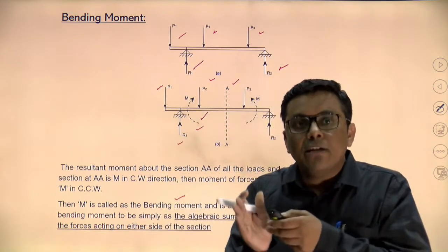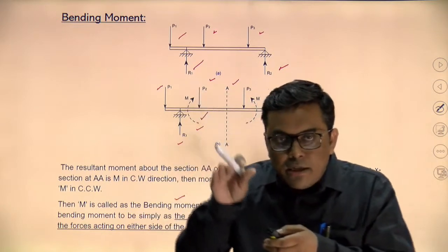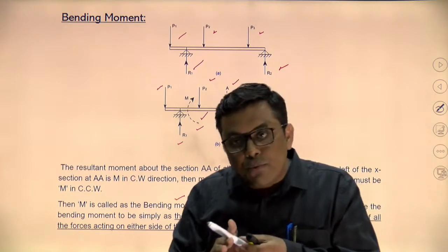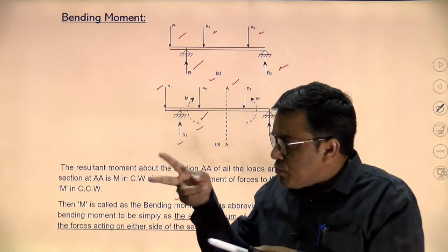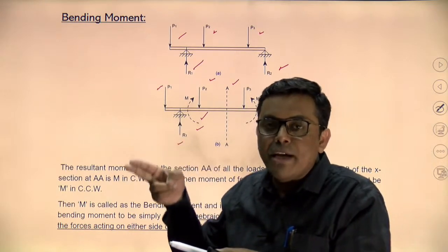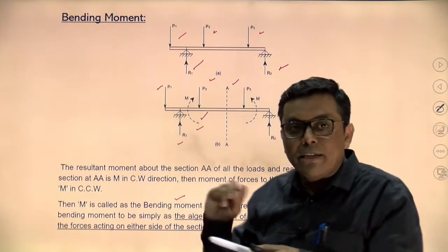On the right side, the opposite of this, for equilibrium purposes. So, on the right side, if the resultant is downward, then it will be considered as shear force, because both will produce a scissor-like effect. If one arm of the scissor is going down, the other one is coming up, it will produce the same effect. So, the same effect will be produced by these two forces.